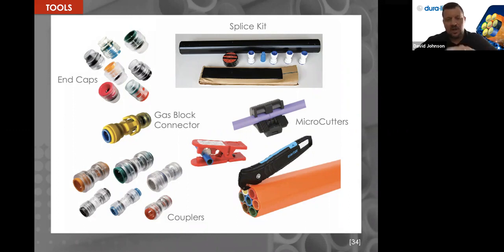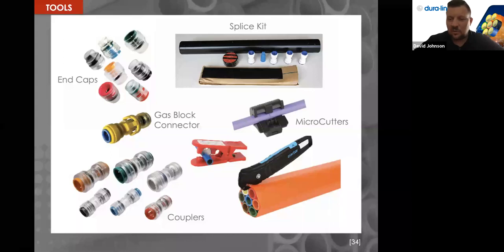And that goes into why you have cutters here. So when you're cutting a microduct, you want to make sure you have a straight cutter, so you can fit that straight coupler flush right into the inside of that. That longitudinal slitter there on the bottom right corner, that's another tool. If rip cords aren't functioning the way that you need them to, that tool allows you to cut the oversheath off, exposing the microducts.